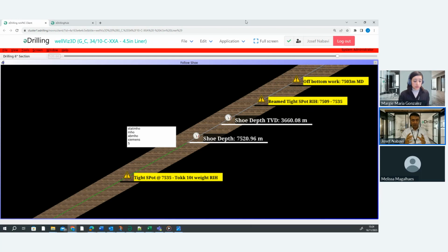During tripping, it runs 12 different simulations, and then picks the best one and adds it as advice to the user. During drilling, it does 64 different simulations, and then picks the best option for the ROP, the flow rate, and RPM. The best combined option of all those three, and then suggests the values to the user.